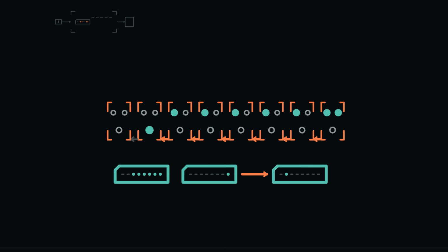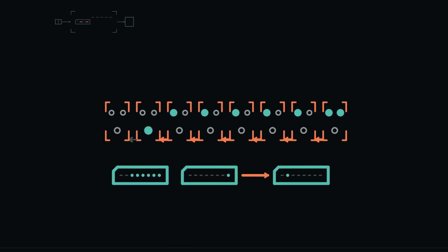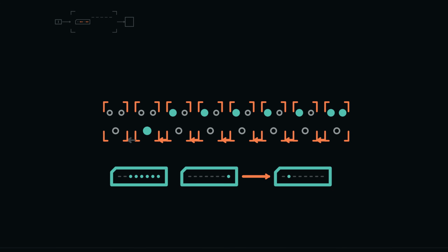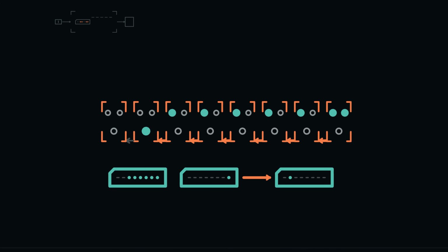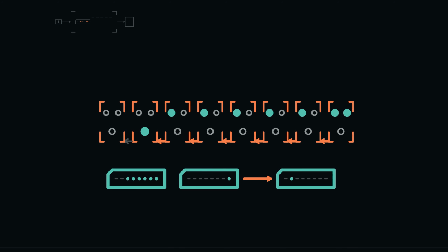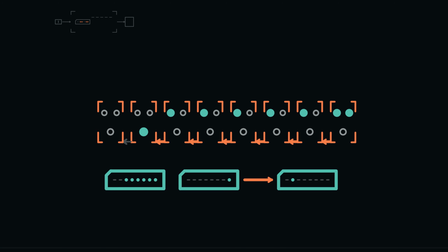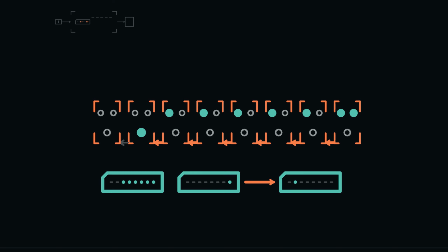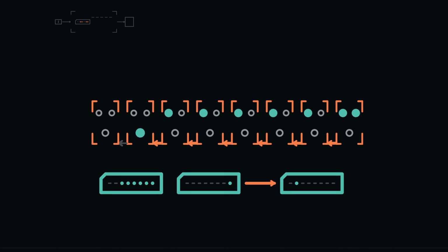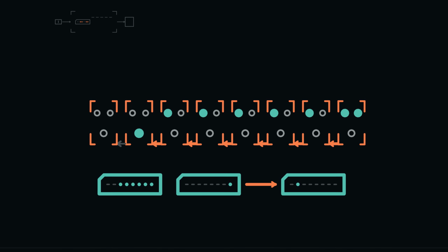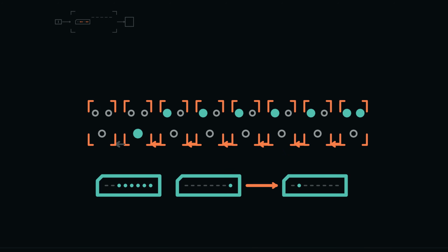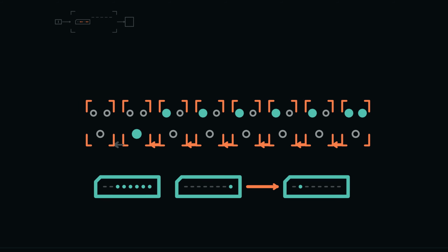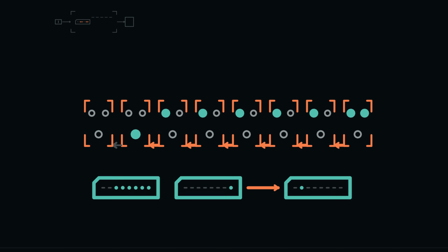Try a new pattern before the carry chain responds. Hexadecimal 3F is 0, 0, 1, 1, 1, 1, 1, 1. Add 1. Bit 0 becomes 0 and carries. Each following 1 also becomes 0 and carries through bit 5. Bit 6 receives that carry. Since both operand bits there are 0, it becomes 1 and carry stops. The result is 0, 1, 0, 0, 0, 0, 0, 0, hexadecimal 40.